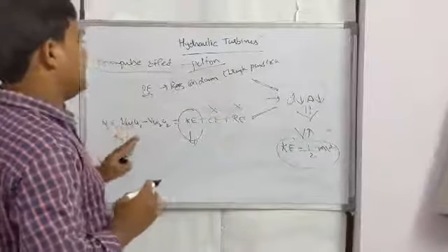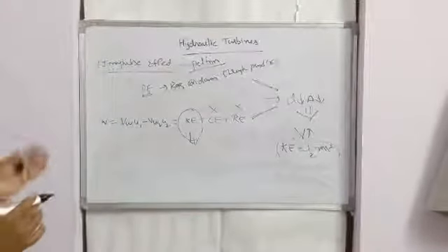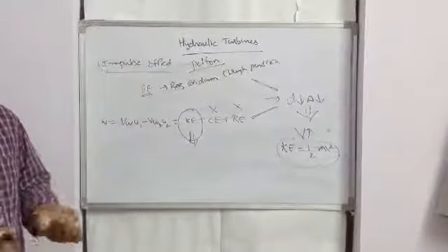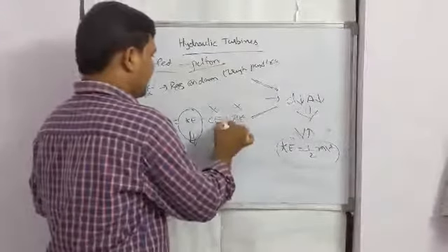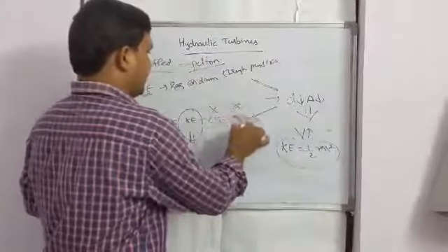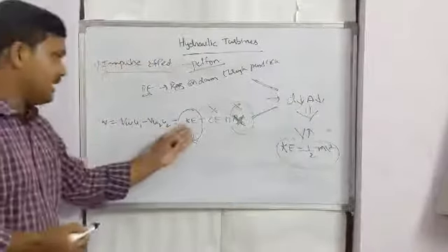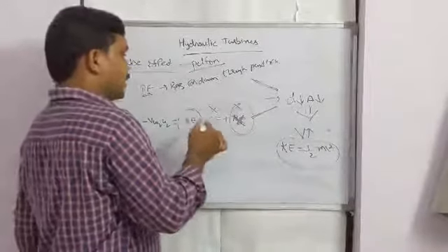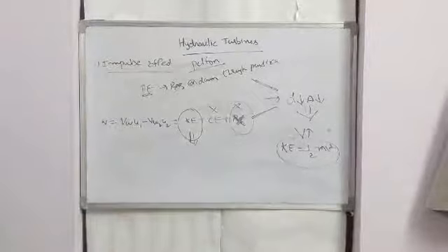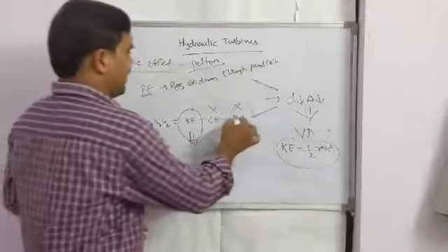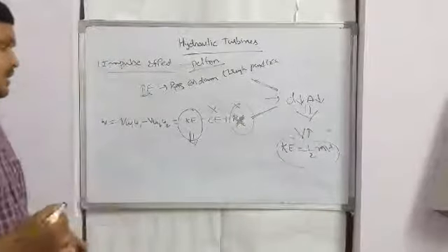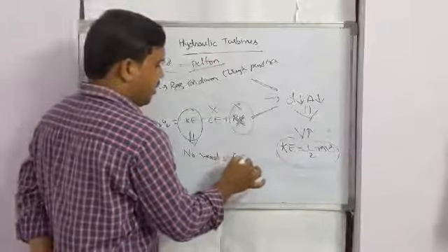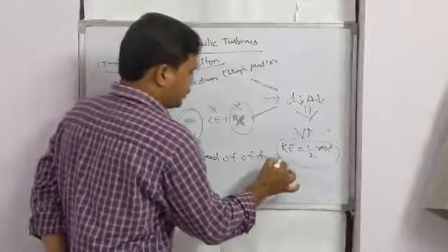There is no change of pressure energy to kinetic energy, or kinetic energy to pressure energy. There is no need of reaction. When there is no need of reaction, only the impulse effect is there. For creating a reaction effect, we have to maintain a closed conduit or a closed sealed environment of the turbine. The Pelton wheel works completely in the atmosphere, so there is no need of a draft tube.